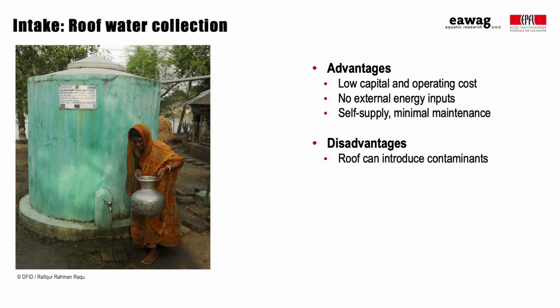There's also the chance of contamination and algal growth within the rainwater tank itself. And during dry seasons or drought, the system may not be used. Overall, rainwater is a good option for supplementing existing water sources if at least 300 mm of rainfall per year is available.